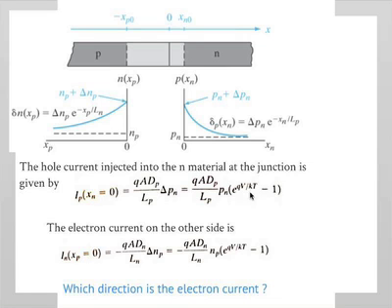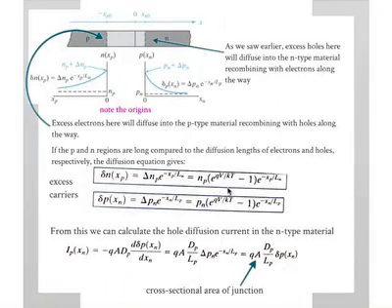Essentially, it's the exponential term. So you can see where that diode equation comes from. The potential comes again from the fact that it determines the probability that the carriers can be injected from the majority side to the minority side. Because remember, it's the energy barrier that determines this injection. So again, you can just plug in the expression for delta P_n from before, which is just this term.